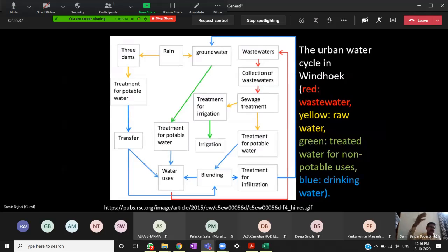Now, groundwater is reaching the aquifer, and what you are doing is disturbing the Le Chatelier equilibrium. You are taking out water, and with water you are also taking out minerals. So what will happen? The surrounding rock will start leaching into this groundwater, and the concentration of all the minerals will become more. That is why there is more and more arsenic, iron, manganese, and fluoride, and all are toxic to us in higher concentration.